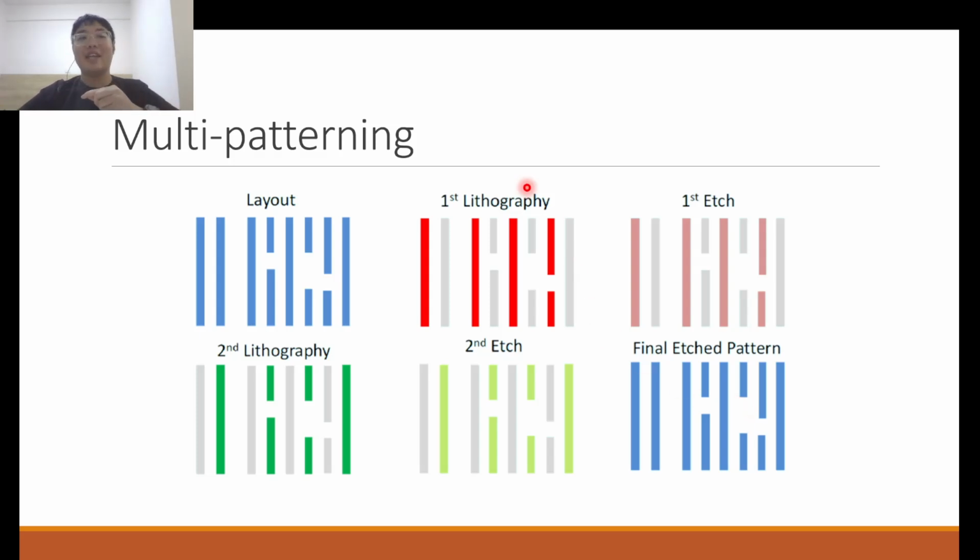So this is actually, if I'm not wrong, based on what is being reported, being used by certain companies in China, because they have been restricted from using certain lithography machines that have the best resolution. So in order to achieve such a resolution with worse machines, older technology that has poorer lithography resolution, they use multiple patterning to achieve these sublithographic dimensions.